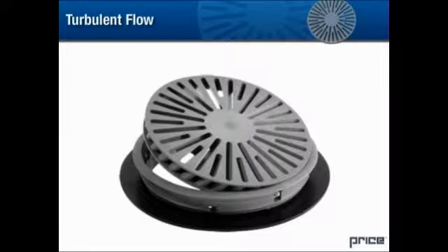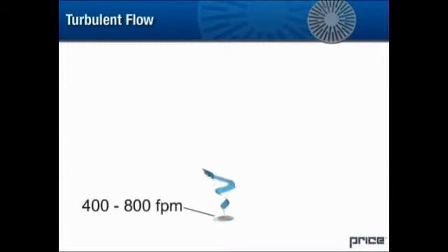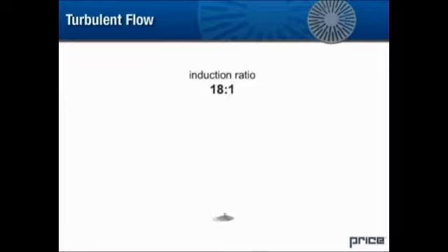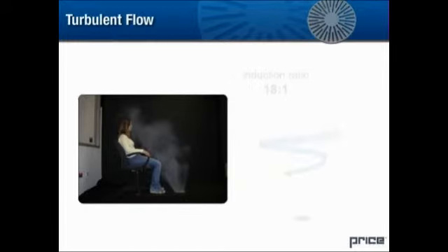An underfloor air distribution system uses floor swirl outlets to generate a turbulent airflow. These turbulent flow diffusers discharge conditioned supply air at elevated velocity, around 400 to 800 feet per minute, at floor level. The discharge is a vertical swirling pattern which rapidly induces the room air. This turbulence enhances the induction of room air and allows occupants to be in close proximity to the supply air